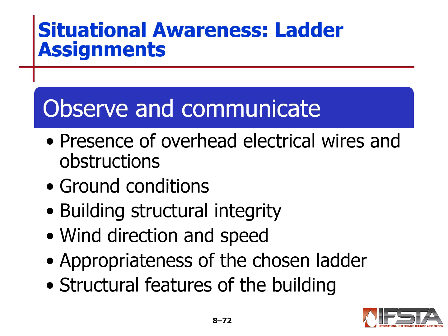A lot of times there's an overhang with a soffit. In a single firefighter raise, you can put that ladder up against the building, but you're only going to get it as far as the soffit. You're going to have to pull it out a little bit to clear that overhang. So that could be a feature of a structure that you have to think about before you go to do the raise.